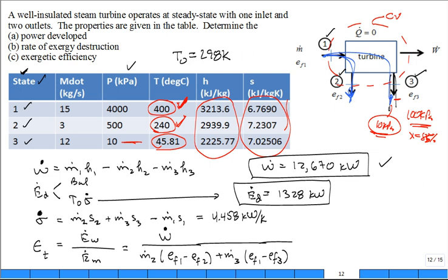Let's go back and think about this. I have an exergy balance equation. I'm looking at trying to do this without using any more real estate on my screen. I'd hate to scroll down. But this power came out of the fluid stream. So this E dot that came out of the mass fluid streams either went into turning the shaft, producing the power, or was destroyed. True? Does that make sense?